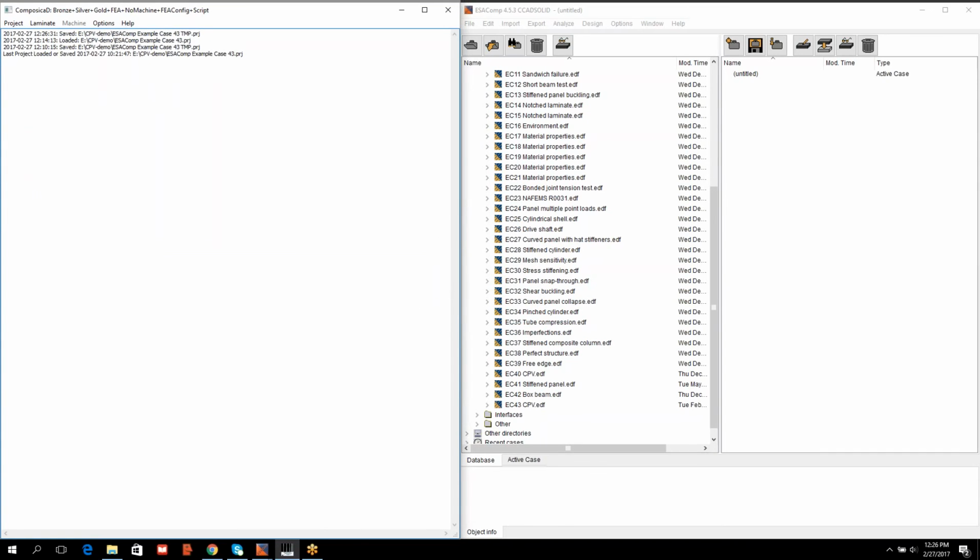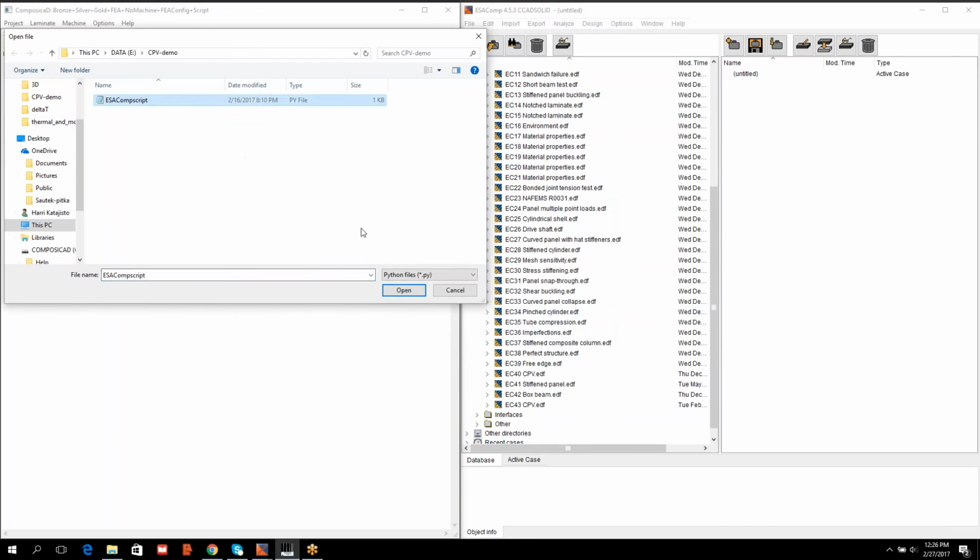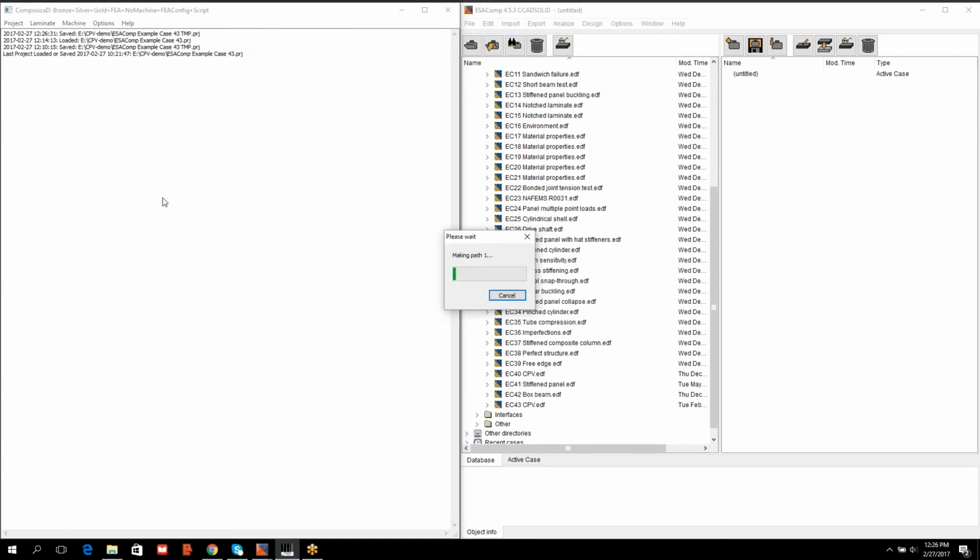Using a Python script, the original laminate table of 18 laminas will be modified. I run a script file provided by Seifert and Skinner. The scripting makes it possible to represent all laminas with positive orientations with unique elements in the true thickness direction of the mesh. The same goes for the laminas with negative orientations. Now the laminate table contains 36 laminas.